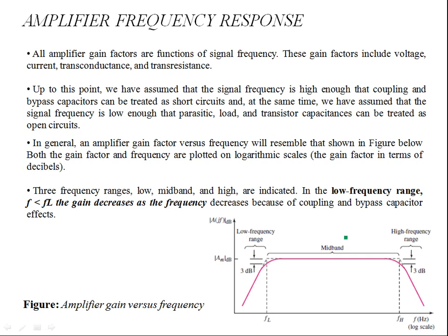For example, we have not included in the AC equivalent circuits the junction capacitances, which are due to the reverse biased source and drain capacitances in between the body of the transistors. And then there are also other gate capacitances like between gate and source terminal, gate and drain terminal. So the effect of those capacitances has never been included in the AC equivalent circuits or any small signal